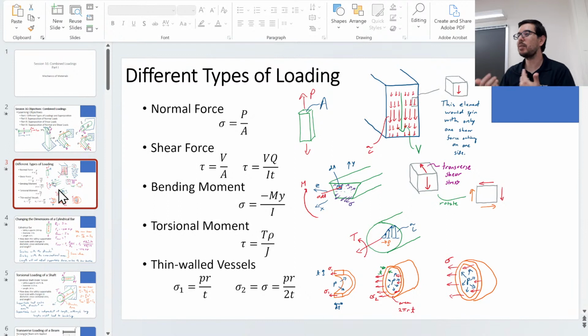So for example, if you have a sigma x and you have a sigma y, for a given orientation of material element, it's important that we keep track. There's a sigma x, there's a sigma y, maybe there's a sigma z too. That's fine, we've talked about stresses on 3D elements in the past. But obviously we can't just directly add sigma x and sigma y to each other. They're not in the same directions.